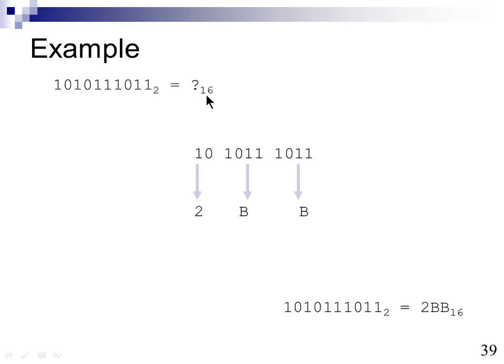Say 1011 1011 10 is the binary. What's the hexadecimal equivalent? The first 1011 goes here. The next 4 bits 1011 go here. The next 2 bits, 10, come here. But it has to be a group of 4 bits to be represented in hexadecimal format. There are only 2 bits in the group on the MSB side, so I add another 2 bits, which are 00. The number won't change. So 1011 is B, 1011 is B, which is 11 basically. And 0010 is 2. So 2BB is the hexadecimal equivalent of this binary.